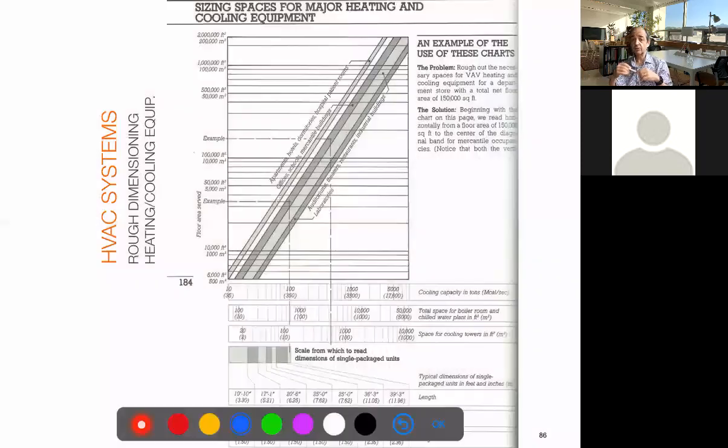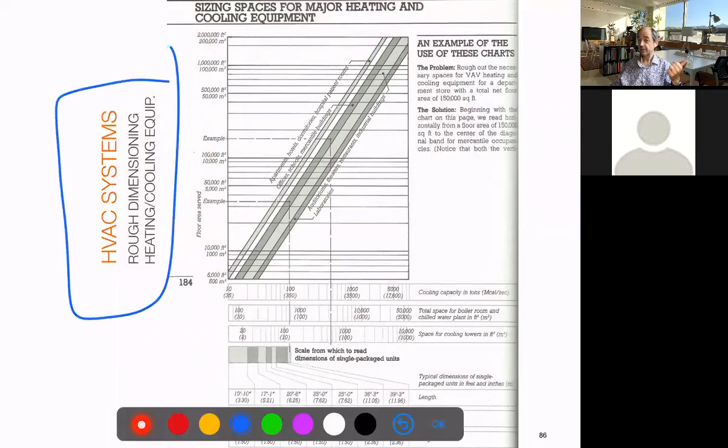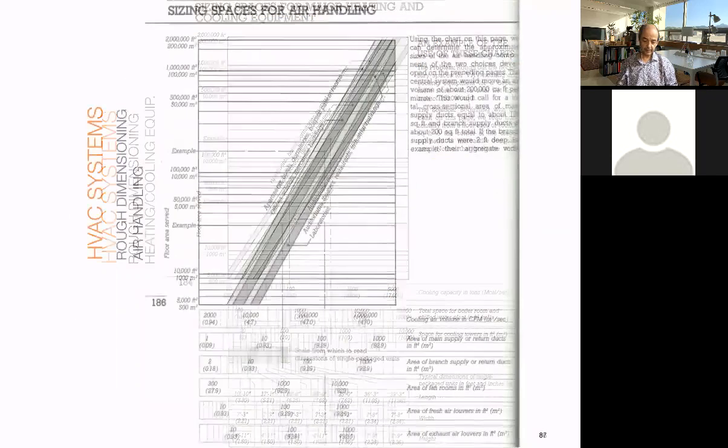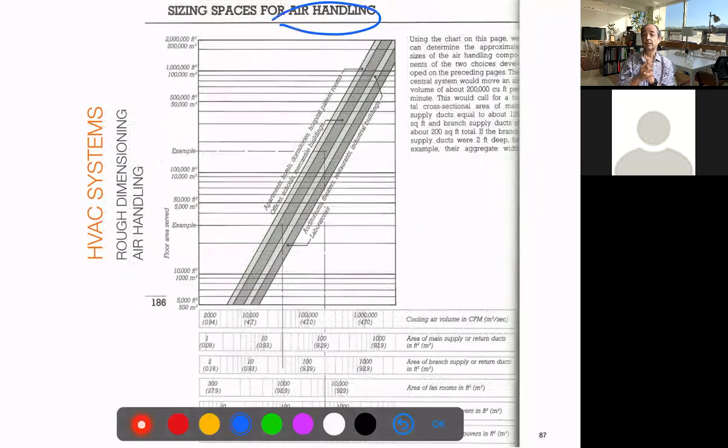And finally, these are the last two slides. I have some tables taken from the reference material. This is, you have an example. I put it here to let you know that you have a table to calculate a rough estimation of that cooling equipment, and you have square meters or megacalories and well, square meters for areas, not only square foot, and also for the air handling units. And with these two tables, you may pretty much estimate all the spaces you need.